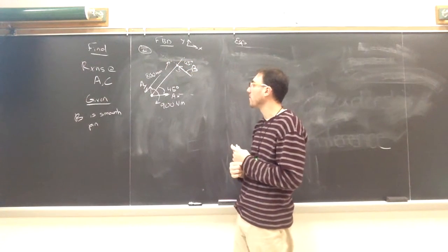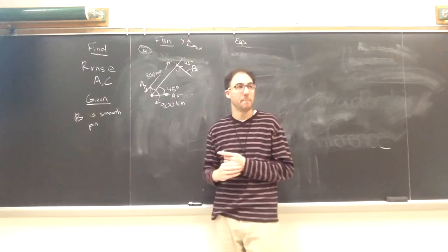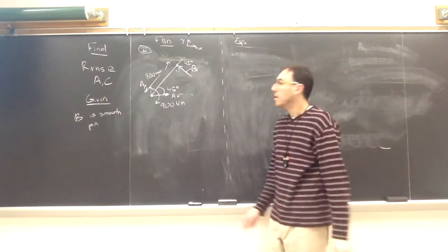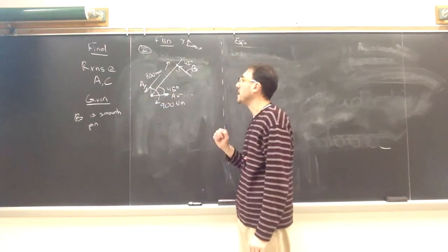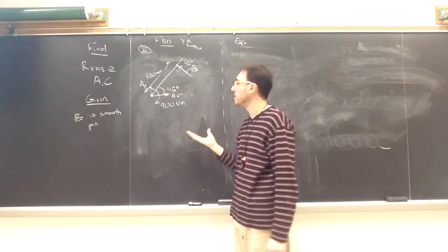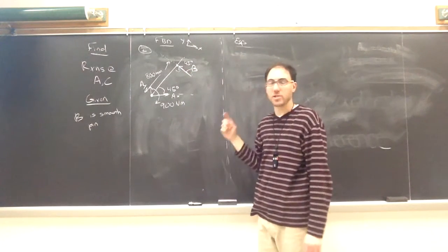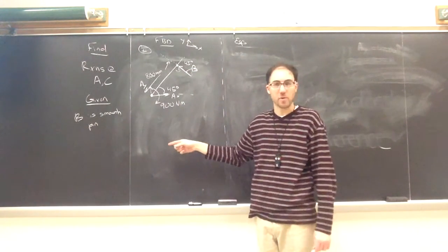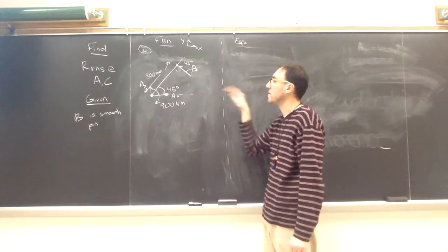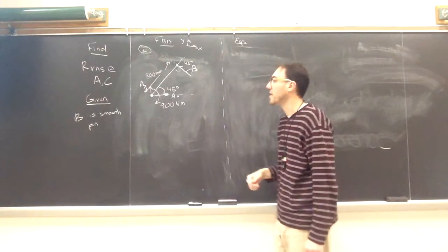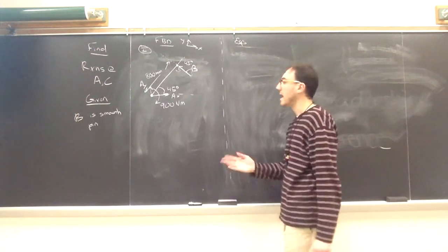So only a single force we should be modeling at B. If we look at this free body diagram, we have AX, AY, and B. We actually only have 3 unknowns in this picture. So I would actually start solving these equations right away before I draw my next picture. It's going to make the process a little bit easier, and we'll see how that works in the next picture. I can solve for the 3 unknowns, so I'll take advantage of that and do that now.